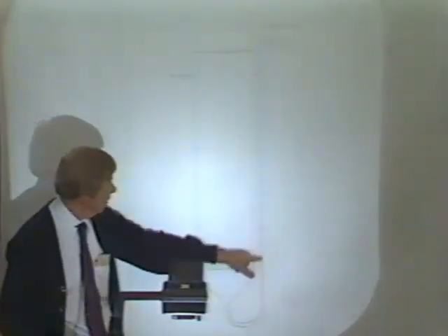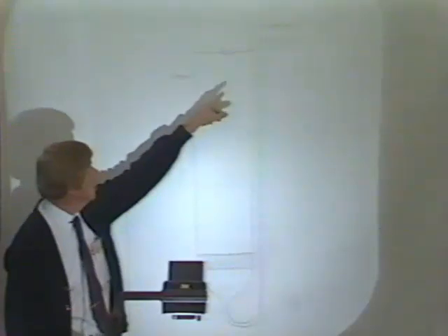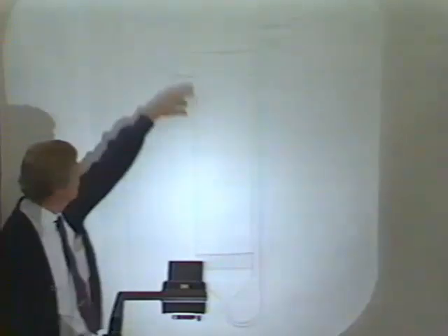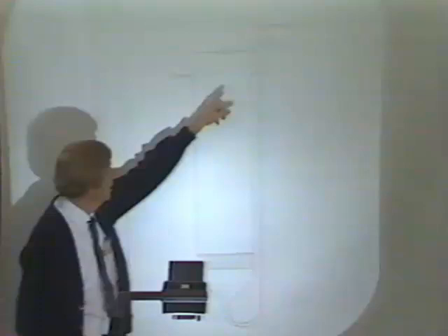And then filled it with salt water. And the first thing we did, of course, was to measure the difference in elevation due to capillary rise on the top. Into these cylinders, we had 3 of them. We put bay mud at 3 different concentrations, and then observed the difference between the elevation of the water here and the difference between the capillary rise, 0 value, and time as a function of time. And what we found was